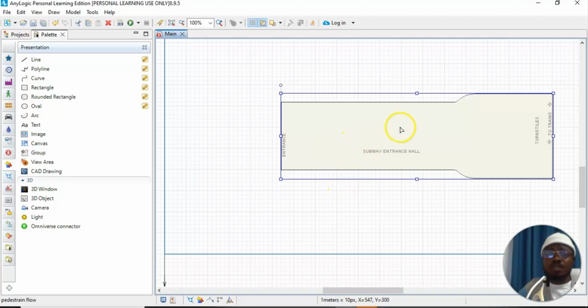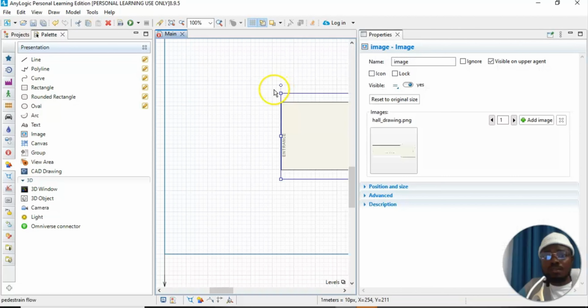So the next thing we're going to be doing at this point is we need to lock this layout, or we need to lock this image. This helps us to be able to keep every information we're going to be putting on this image there. So there won't be any case where some of this information might leave. So we just need to lock this in order to be able to add other elements to the image. And in order to do that, you can come under view where we have the properties. So here we have the lock.